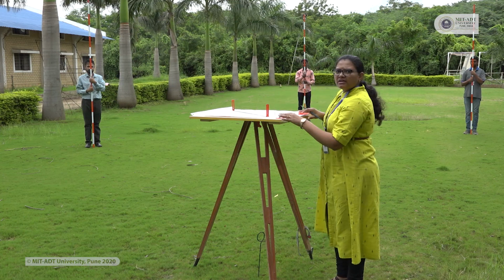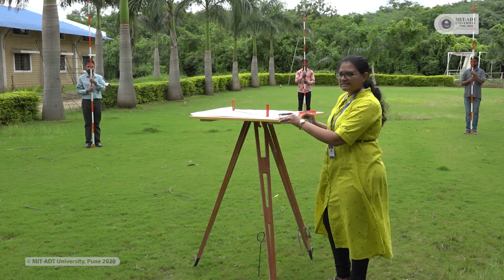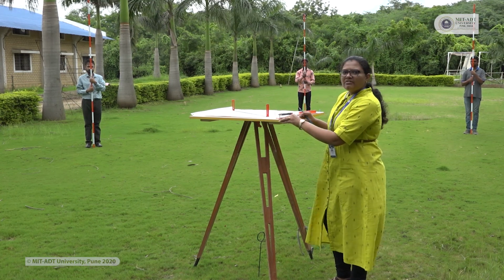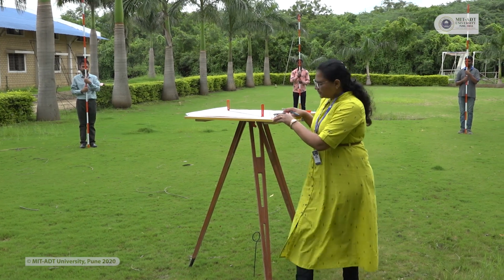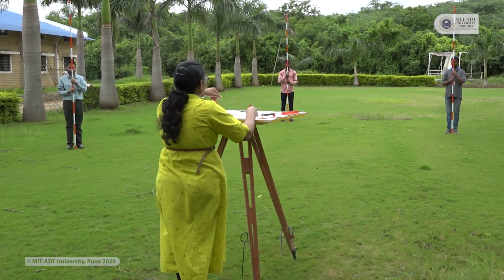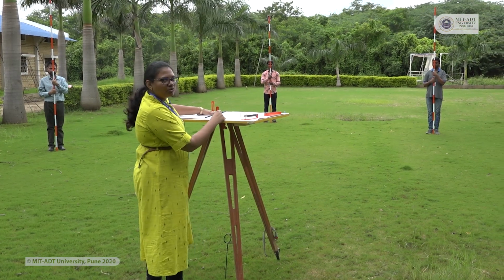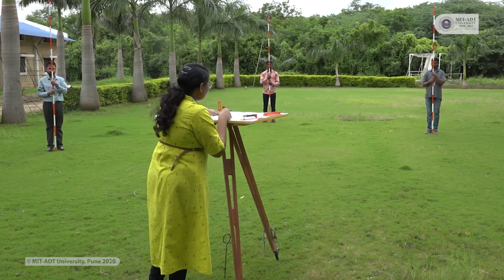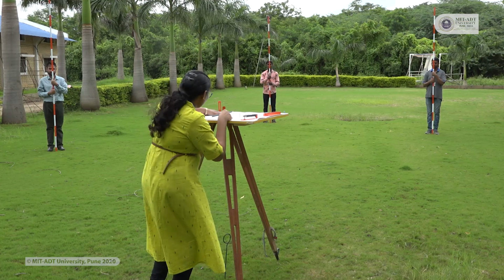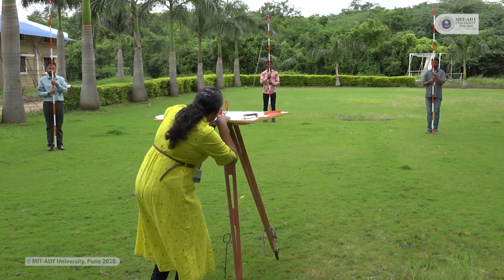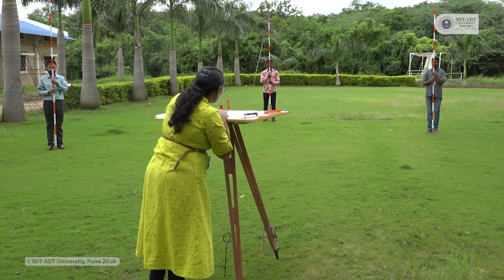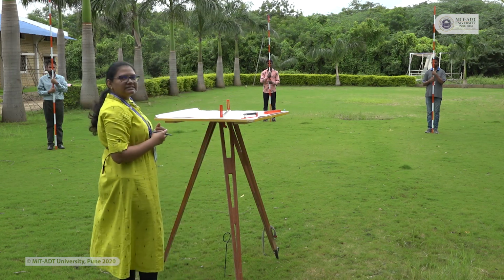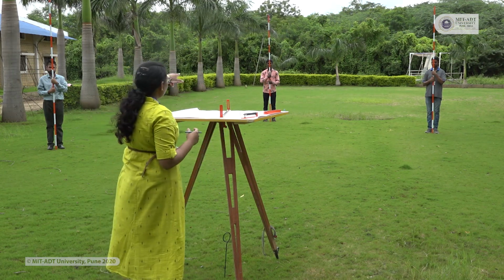So this is my marking of station number 2, that is station point B. Now I will mark 2 objects which we have to plot on the paper. I will bisect the point P. Again the rays will be drawn from the same station point. My line of sight is very straight. It is marked with the P point.